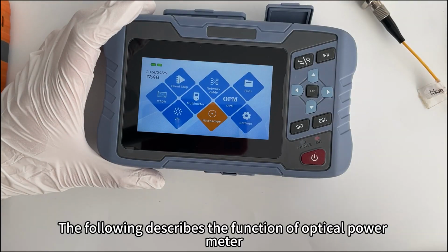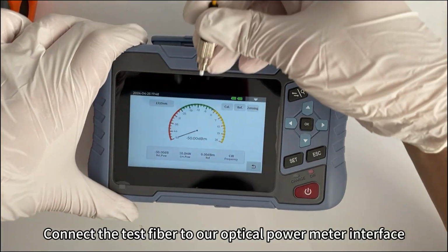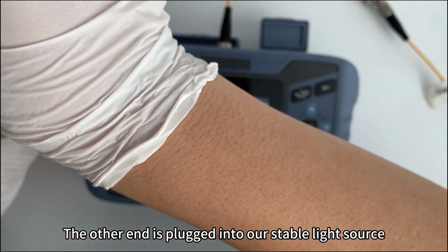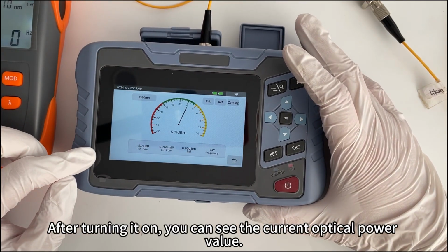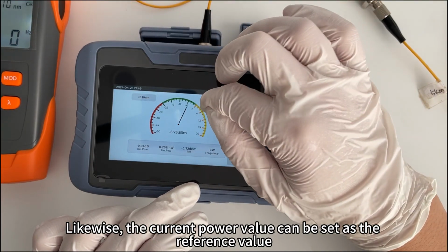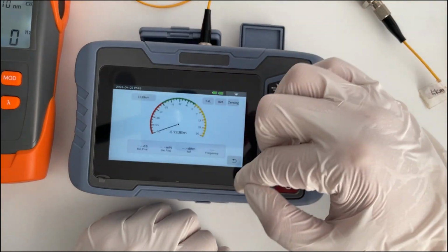The following describes the function of optical power meter. Same. Connect the test fiber to our optical power meter interface. The other end is plugged into our stable light source. After turning it on, you can see the current optical power value. Likewise, the current power value can be set as the reference value. Click Calibration to calibrate the power value.